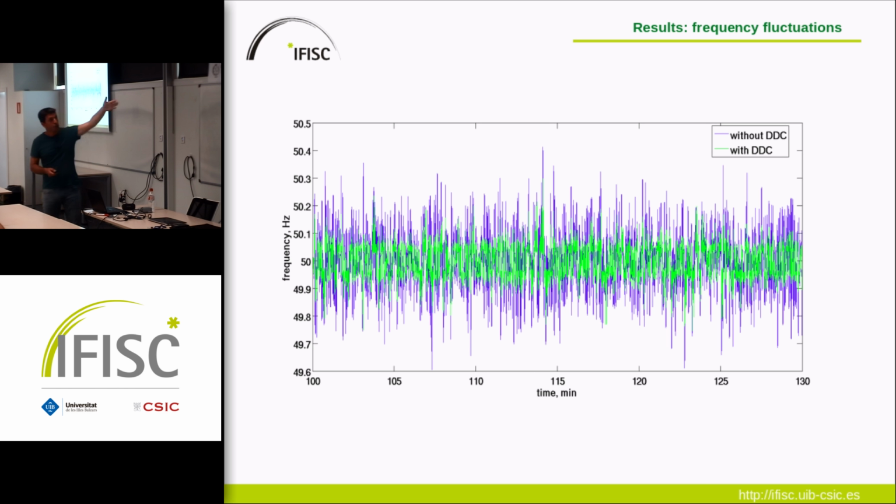And this is how it looks now. Blue is without control. Now you put the dynamic demand control, and the frequency is in green. Clearly, you have reduced fluctuations. So the system works much better. Okay, so we're happy, but you can see here some green, you still have some peaks. You can never get rid of these, let's say, rare events. Sometimes, stochastically, it happens that when you recover, many devices switch on together, and you have a frequency peak, and that's not good. Because it's actually large, and we want to avoid that.